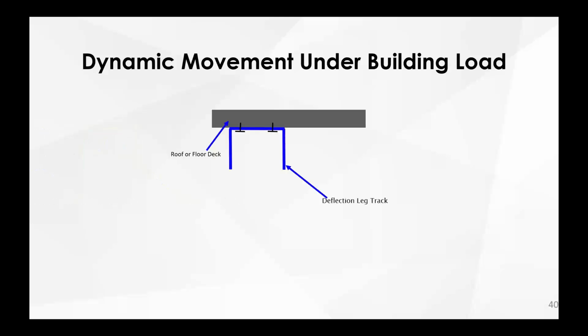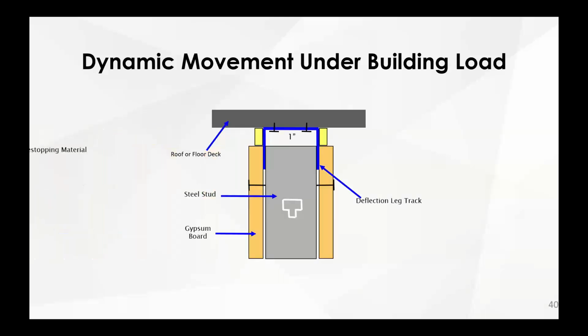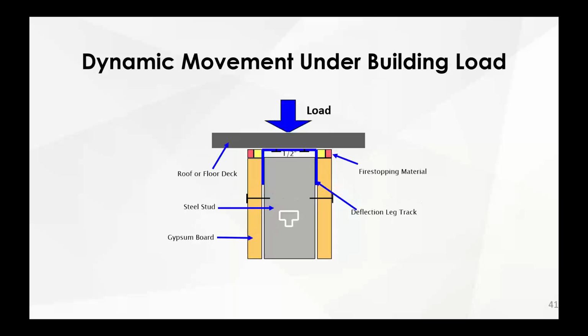Okay, so this is the movement I'm talking about. This is dynamic movement under a building load. You notice a couple things. The stud is placed 1 inch down from the top, so when that ceiling comes down and compresses, it can go down and go back up. That's what they're looking for, down and back up.